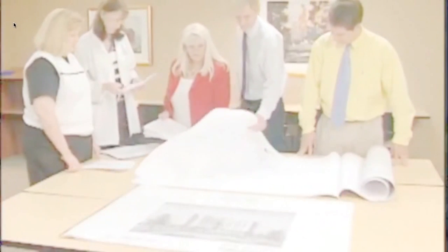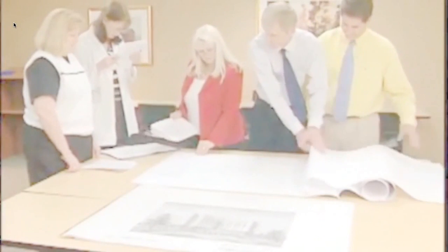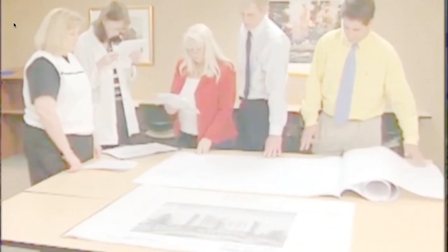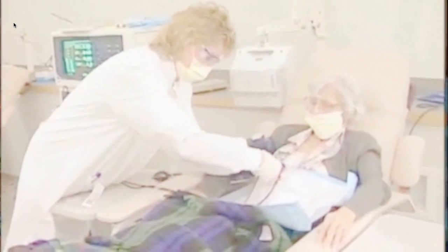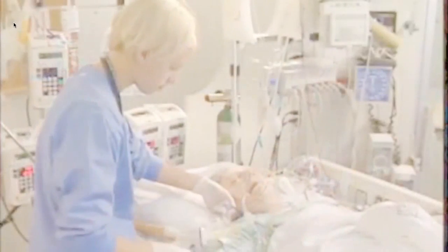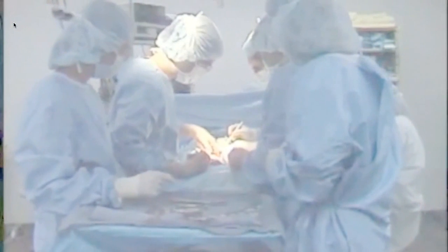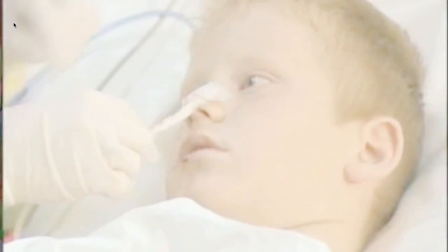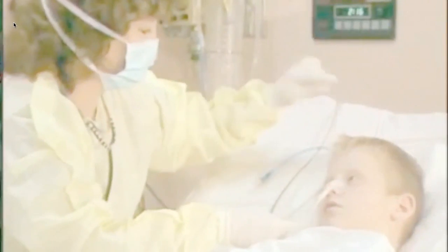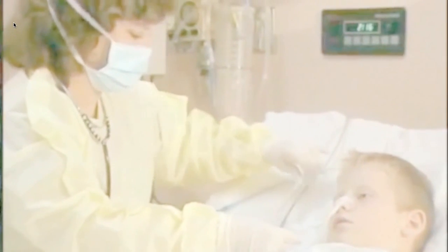Once the project activity has been defined, Step 2 of the ICRA identifies the patient risk group. This is the group of patients most likely to be affected by the type of construction or renovation activity identified in Step 1. Patient groups are ranked from those at highest risk of infection to those at lowest risk, based on the patient care area.